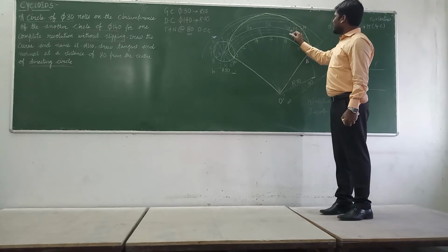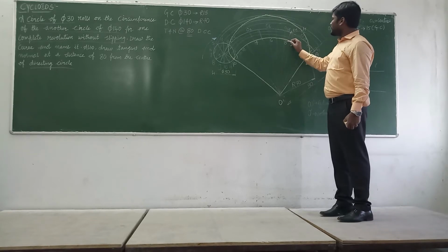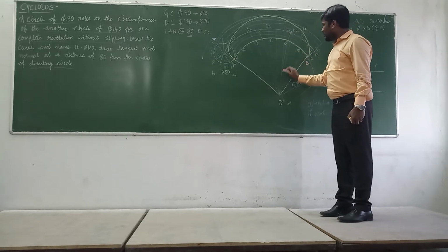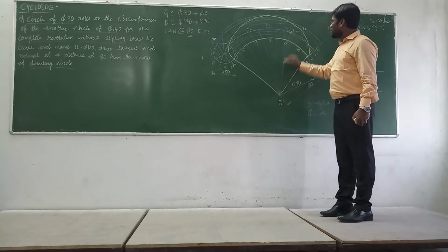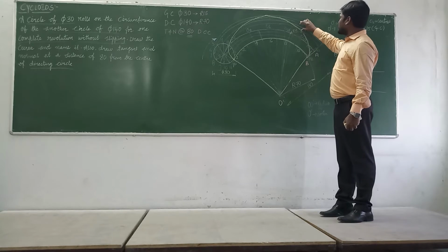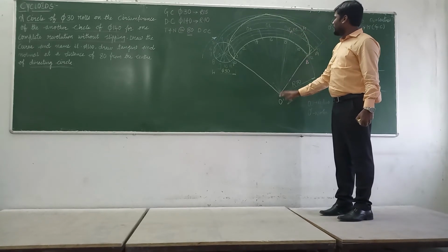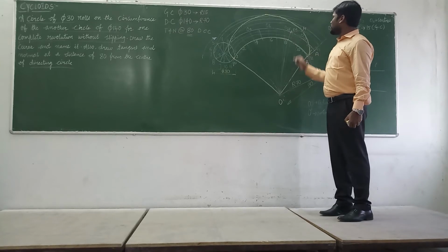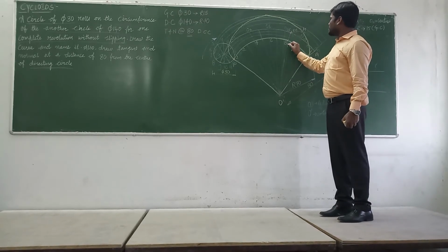Then draw a line onto this directing circle and further extend it down parallel with all these lines. Extending it down. What I did? 80, locating point M from the mass center. Radius is 15. Cut the locus of center. Drop it, whereas the line is touching the directing circle here, that is N.